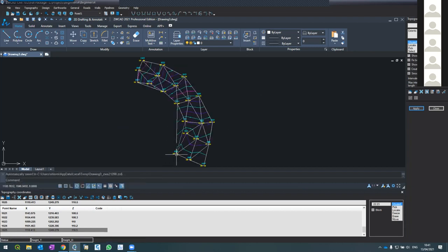You see, now the software added this triangle because the distance from here to here is probably shorter than 110. So we can play with it until we find a good solution. That's fine. Let me remove the maximum interpolation length and press apply, meaning it's not applicable. So we finish with the border problem.